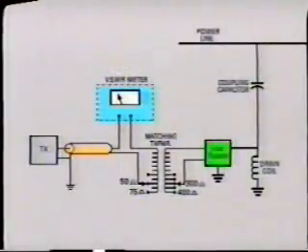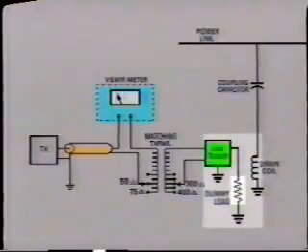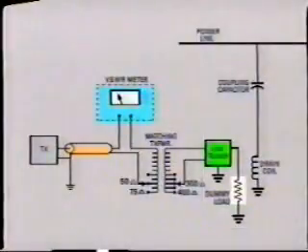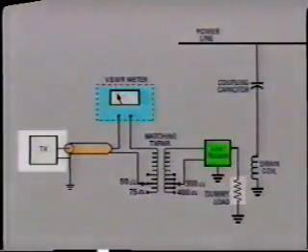This is not so easy where several transmitters are connected, operating at different frequencies. One way of handling this is to connect the LMU into a dummy resistive load equal to the line impedance and adjust the impedance matching at the carrier equipment for each different frequency.